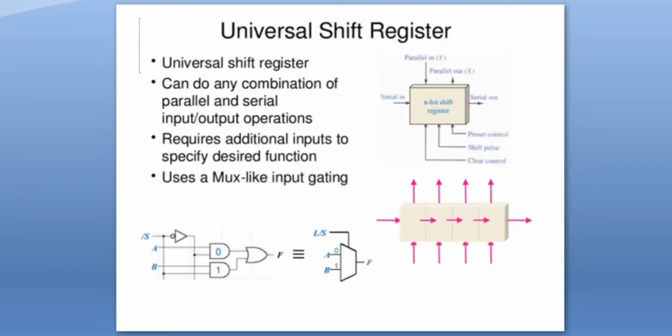So now what happens, directly we are going to give the value here. This S bar value we directly connected here. So 0 and 0, both the things will be 0, and 0 and 0 means 0. So both the AND gate outputs are 0, and we are going to get the output as 0.